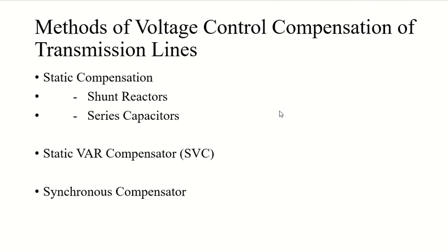When your system voltage becomes lower than nominal voltage, the additional equipment which is connected to the system will start to generate the lagging VAR, right? In order to meet the requirement of reactive power of your load, so that the voltage can be maintained on different buses within specified limits.